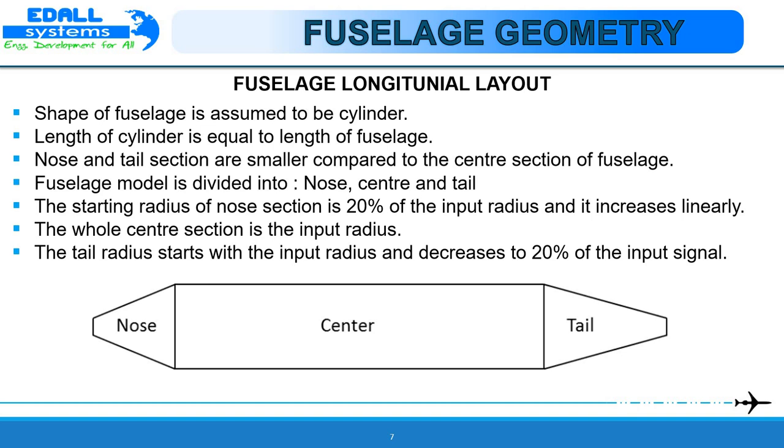The larger the fuselage, the more payload you can take, and this is at a high comfort. However, a smaller fuselage will also mean less drag. Remember, even though payload is the driving factor, you are still interested in other requirements such as range. The exact diameter and length of the fuselage will be our first dilemma. Since it causes 20 to 40% of the total zero-lift drag coefficient, an increase of 10% in the diameter yields a 2% drag increase.